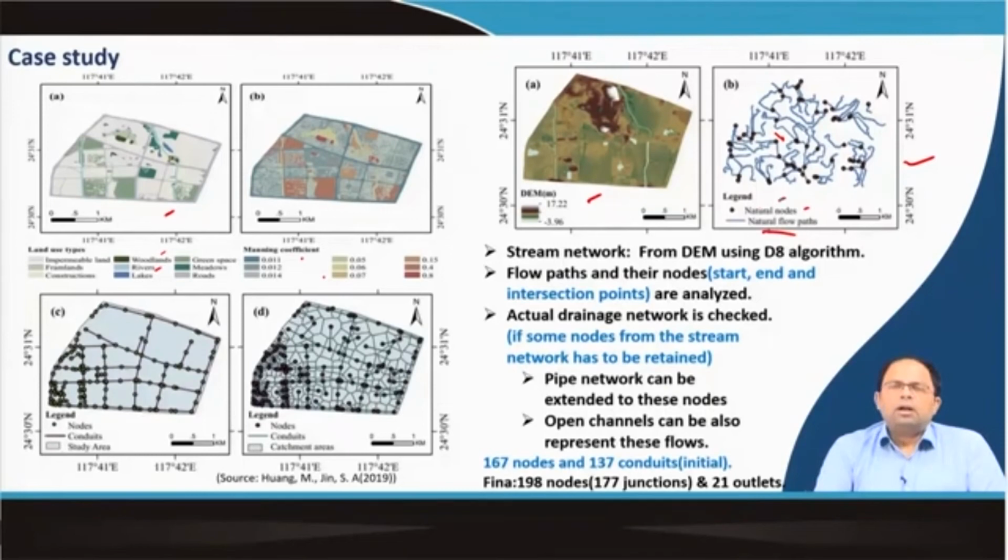This actually shows in which direction the water will flow and along which channels the water will flow. But this is good for larger catchments or larger areas. In urban areas, particularly in flat terrain areas, we have to depend on node-based catchment geometric methods of catchment determination, and this is what has been done. So, this is the sewerage network or the stormwater network in that urban area, and for each of these points we determine the Thiessen polygons,